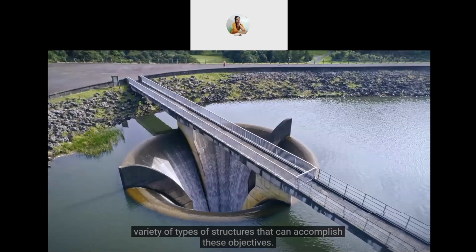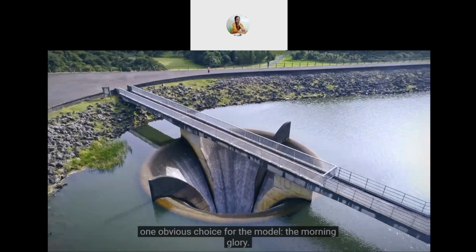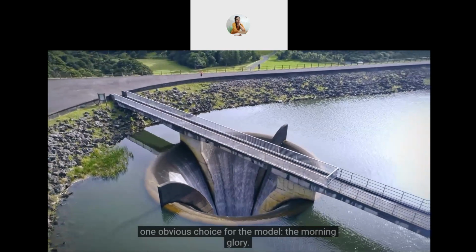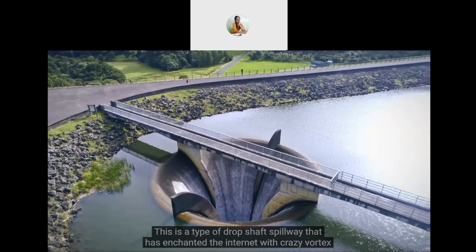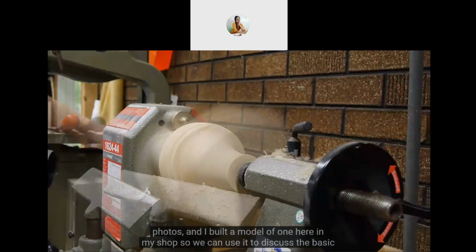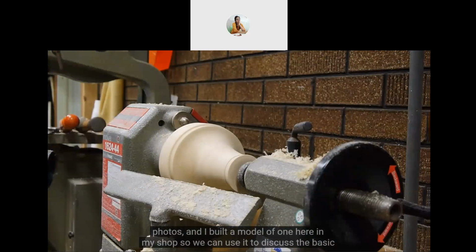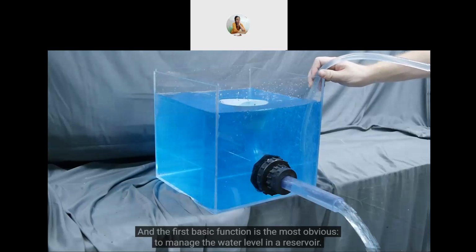But I think if you're going to demonstrate a spillway on the internet, there's only one obvious choice for the model: the morning glory. This is a type of drop shaft spillway that has enchanted the internet with crazy vortex photos, and I built a model of one here in my shop so we can use it to discuss the basic functions of a spillway. And the first basic function is the most obvious, to manage the water level in a reservoir.